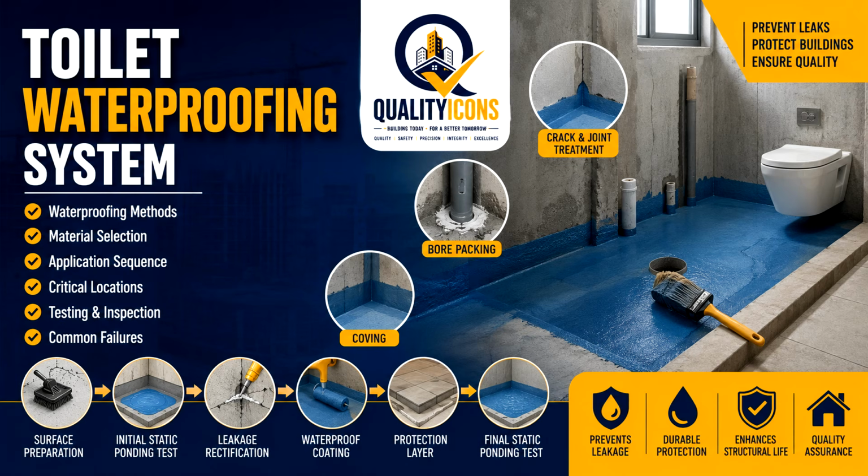Toilet waterproofing is not simply a matter of applying a coating on the floor. It is a complete quality control system starting from surface preparation, followed by bore packing, initial static ponding, leakage rectification, crack and joint treatment, coving, waterproofing coating, protection, and final ponding. Our objective is simple: prevent leakage before the toilet is handed over. Let's begin.